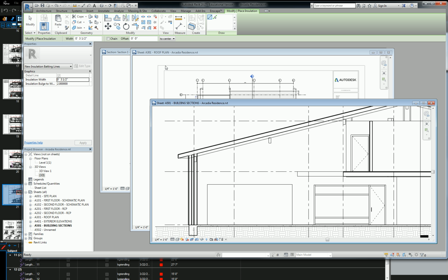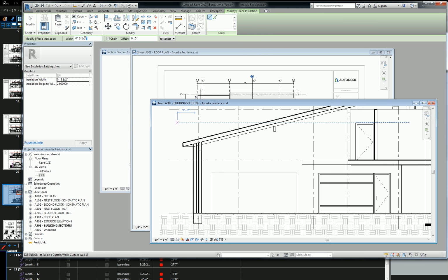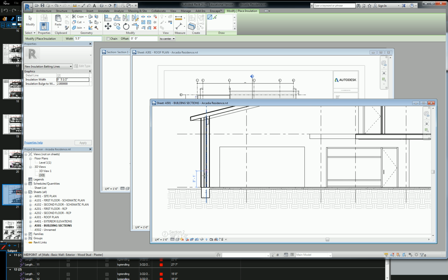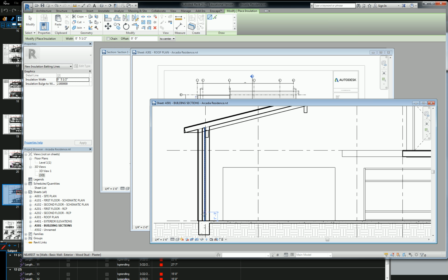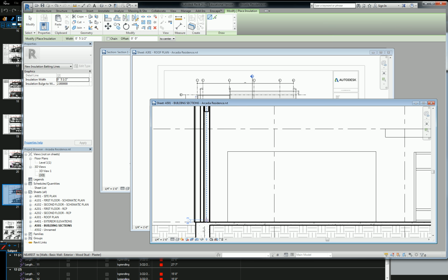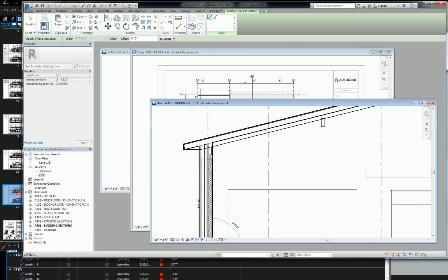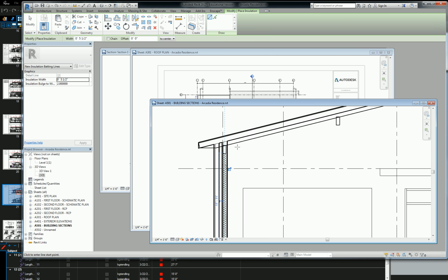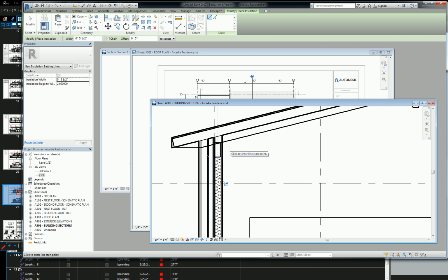It's awesome. So our exterior walls, I think, are 6 inch wood studs, so we're going to do 5.5 inches under the width thing there. And I'm not entirely sure where the insulation is going in his drawing, but I'm going to use the inside wall because I think those exterior pilasters are purely for design. So insulation is not going to cross over structure. It's one of those finesse things that I think ties in the illusion of detail really well. So try your best to skip structure.